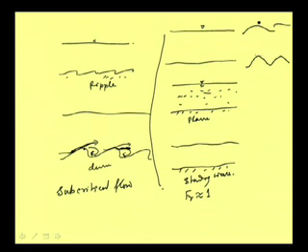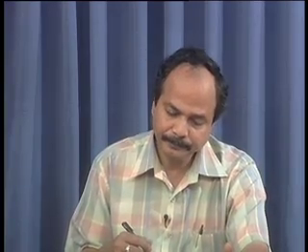Well, now the one difference is there. In case of ripple, this crest is moving in the forward direction, but in case of anti-dune, although the sediment is moving in the forward direction, this crest is moving with a very slow speed in the reverse direction. So, that is why the name is called anti-dune, where the surface can also break. Well, like that we can have different sort of flow regime, as you could see that all these different kinds of flow regime we can have.